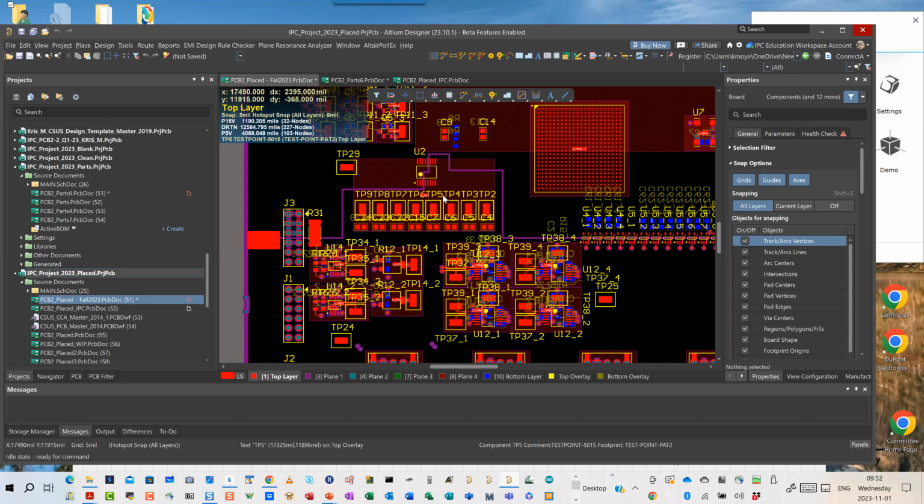Most A to D converter chips I've used on the market will take the time to go to the next larger package size, like 16 pin instead of a 14 pin, so that they can make sure that all of the analog reference pins are on one physical side of the chip and all the digital reference pins are on the other side of the chip. This particular one split it a little differently. They've got analog pins here and digital pins here and here.